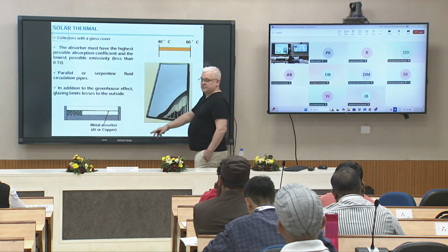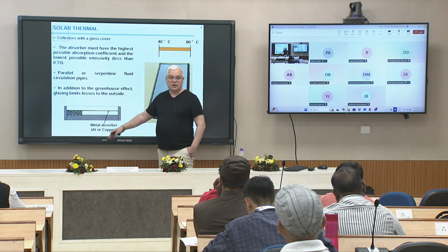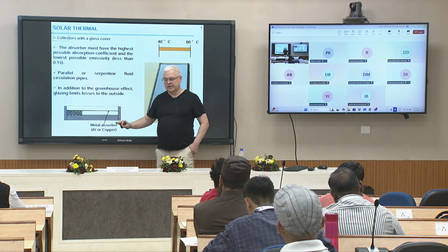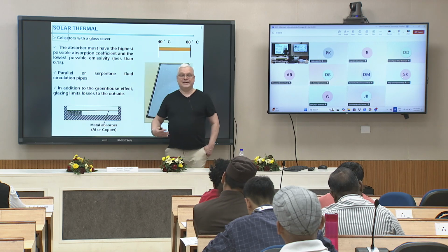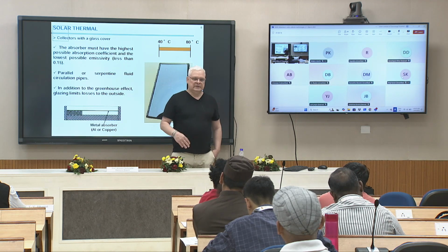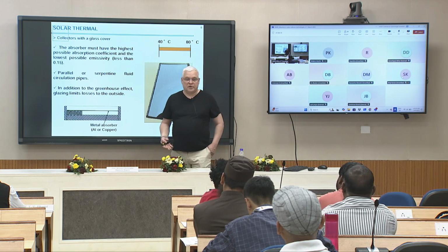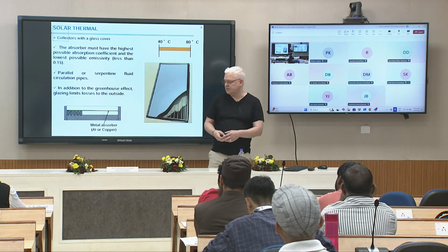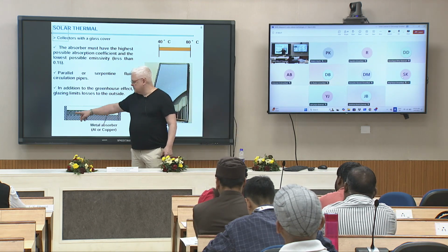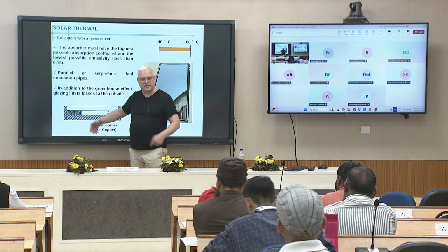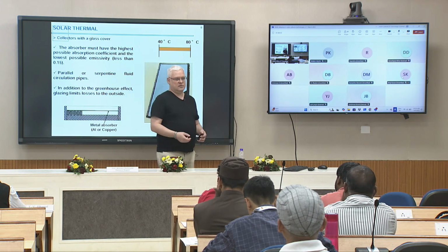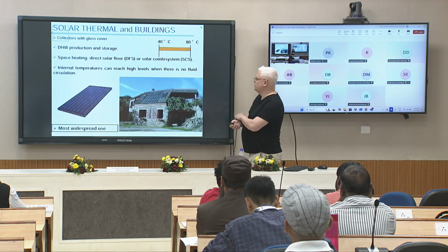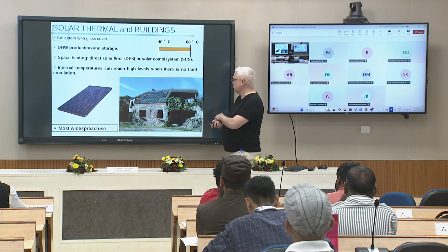And also on materials, because as I told you, plate of copper now is expensive, even if it is very thin. So we try to find alternative materials that are not as good as copper in terms of heat transfer, but are less expensive. So to find a compromise between the enhancement of heat transfer between fluid and the absorber and the quality of the materials of the absorber. It's a big issue. Some nice integration in a house